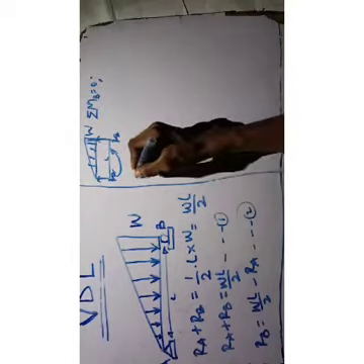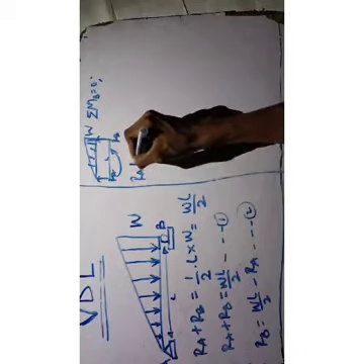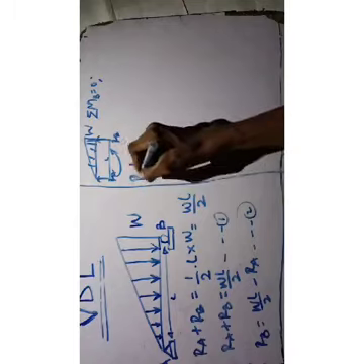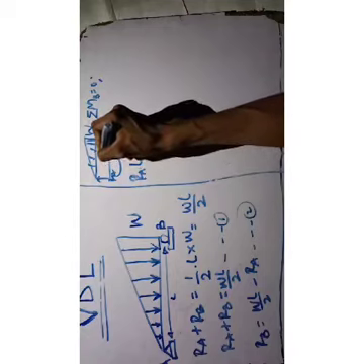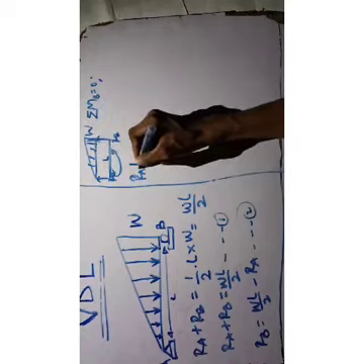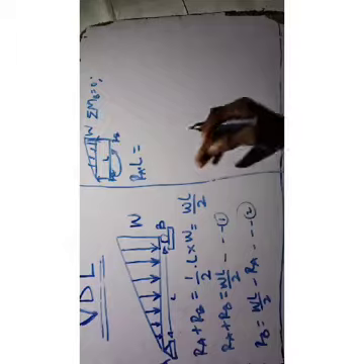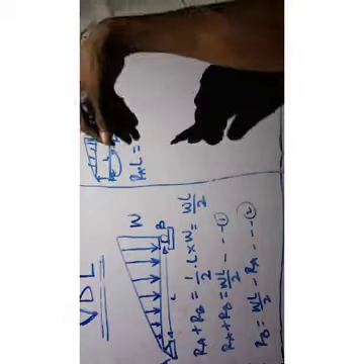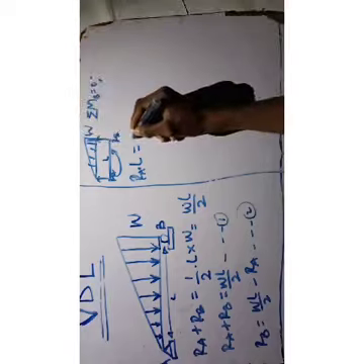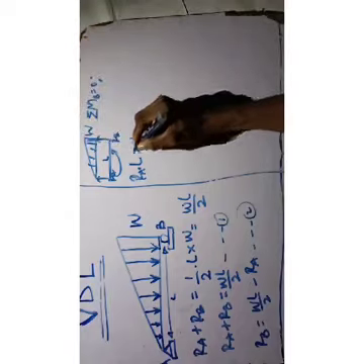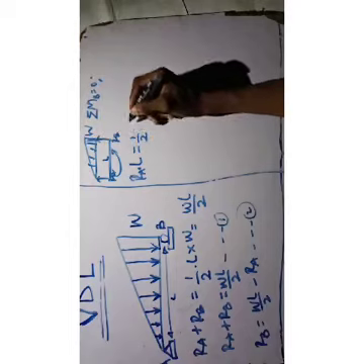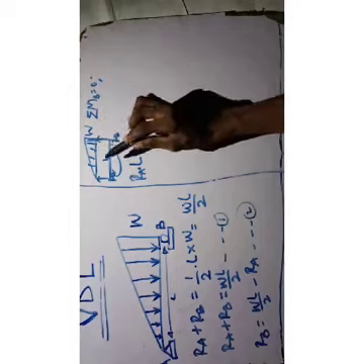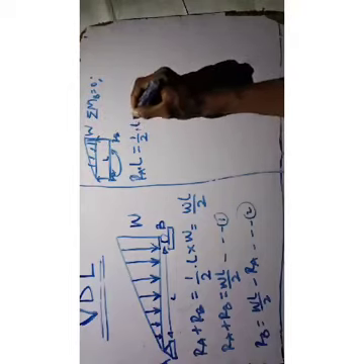So I have RAL, that is force times distance, the total length, equal to, clockwise equals anti-clockwise, RAL equals, turning this to a point load gives half base. What is the base? The base is L times height.